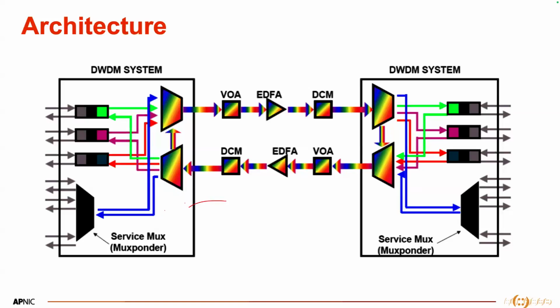It doesn't matter what name a vendor gives their card; they should have FEC, a specific range of supported lambdas, and specific transmit power for lambdas. They should have a similar kind of data sheet, with figures that vary from vendor to vendor.